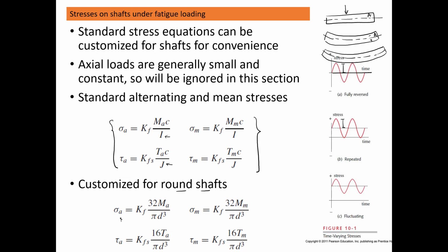what we have is A becomes down here. The shaft rotated 180 degrees. Sorry, this is tension. So you can see point A, which is the upper portion of the shaft, will start fluctuating between plus and minus. This is fully reversed because nothing has changed in terms of the load.